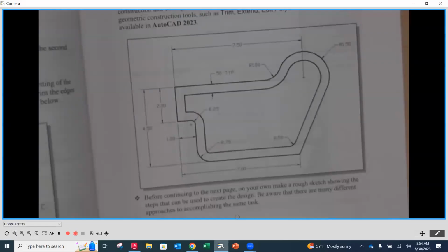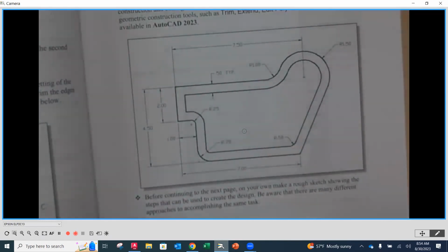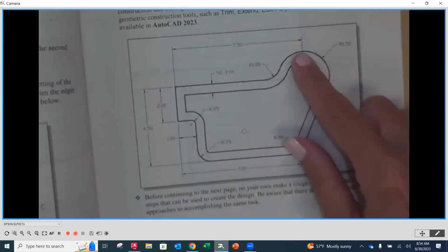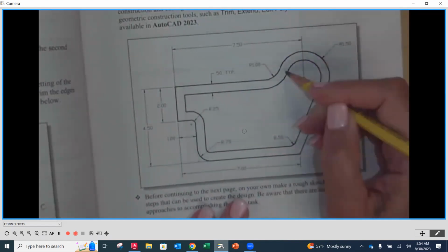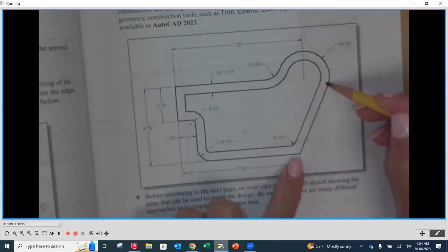So let's go back to our drawing. So we have created kind of this path on this side and then this horizontal line to a random length, okay? Now, I need to create this circle because then I'm going to trim this line and then I can also add the line from there to be tangent up.